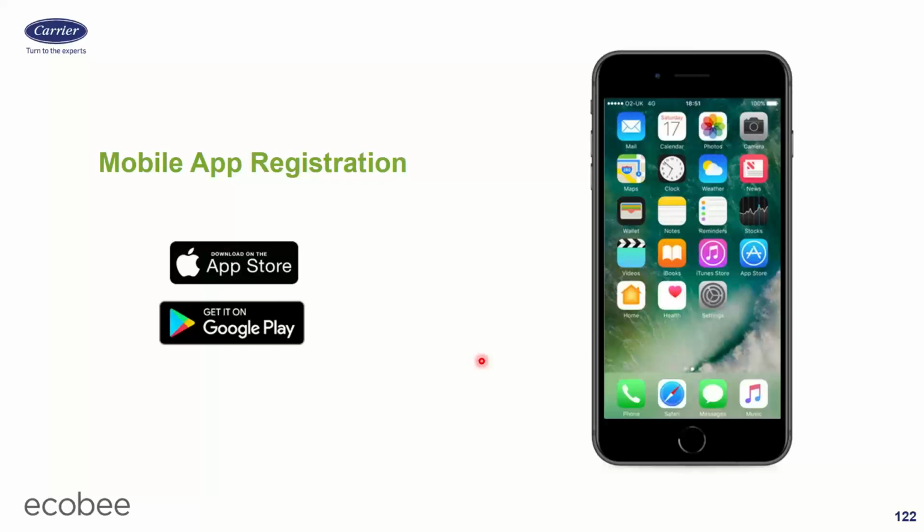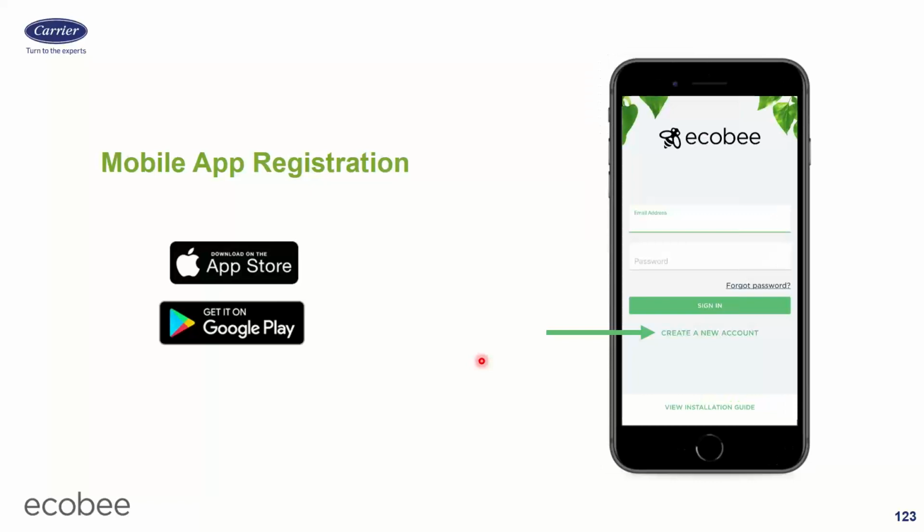You may be doing new construction, installing the stat, and they're not going to have Wi-Fi for like 6 more months or whatever, right? That's fine. Once again, it'll have to just run in a basic regular thermostat mode. Although personally, if it was me, I would put a cheap thermostat on the wall and wait until the homeowner's almost moved in before I put the good stat on the wall. Just because I don't want it getting full of drywall dust or getting smacked around and hit with ladders, et cetera, et cetera.